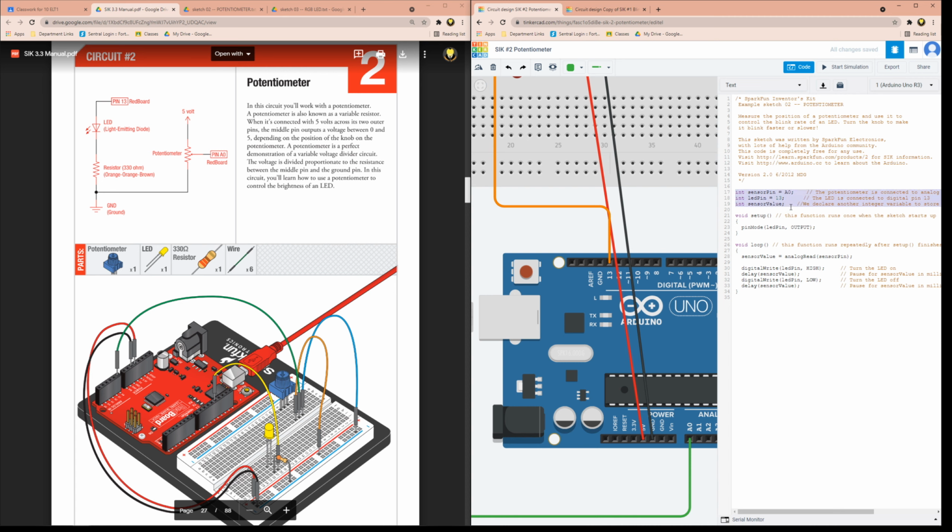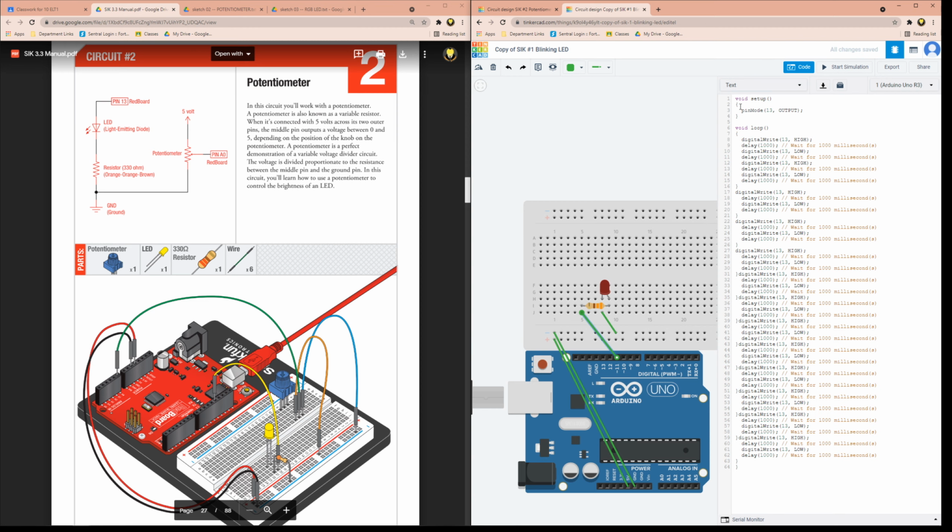We're saying over here we have integer. Over here, the void setup, we have only one pin to care about. Pin mode, we're saying that our LED pin, so pin 13, is an output. We're declaring that. I believe you just have to declare, and we'll get up to this in later tutorials if I'm incorrect, but I think you only have to declare for digital pins. So we're saying pin mode, pin 13 is an output. This is the same as our previous code.